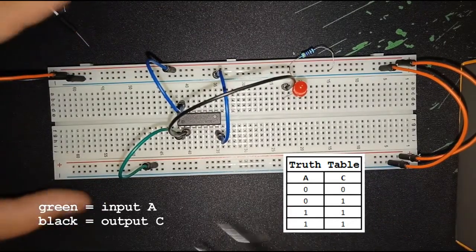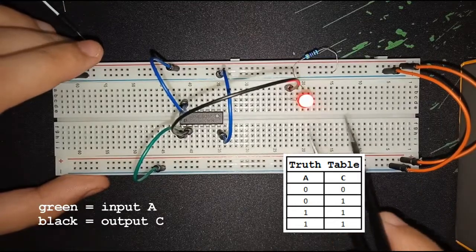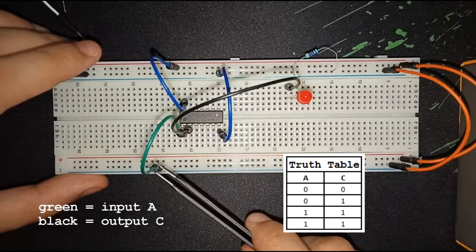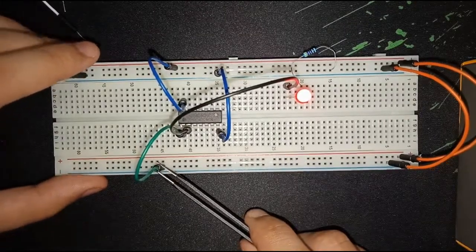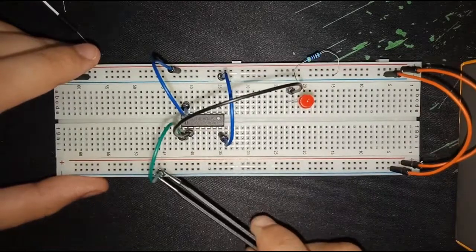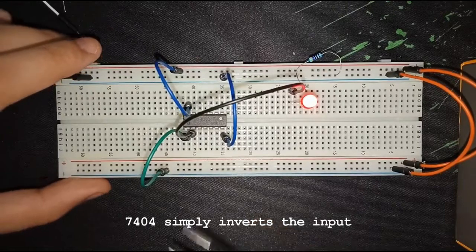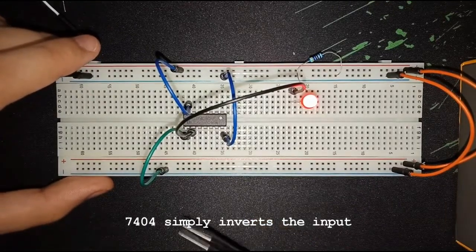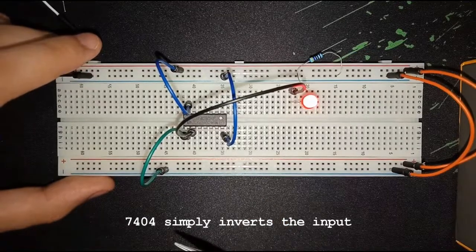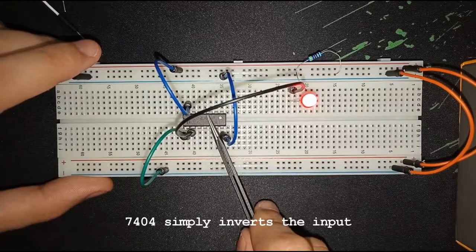So from 1 to 0. So the result of that is it switches off. And then if you move it into 1, it becomes 0, and then 1 again. So therefore it lights up. So this is the example of your NOT logic gate, which is the number 7404, that simply inverts the input. So that is your NOT integrated circuit.